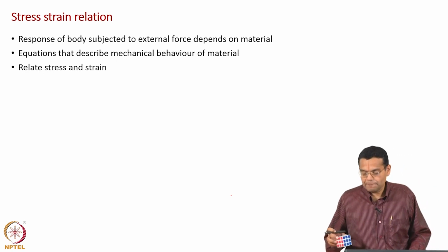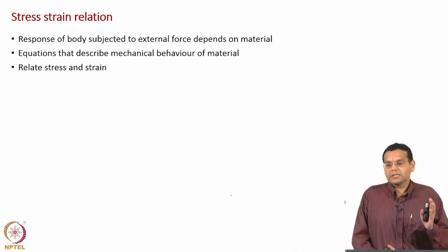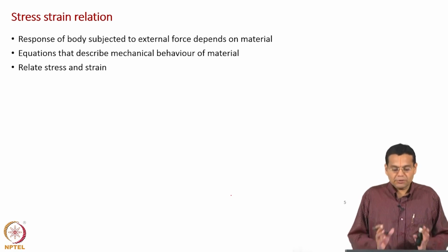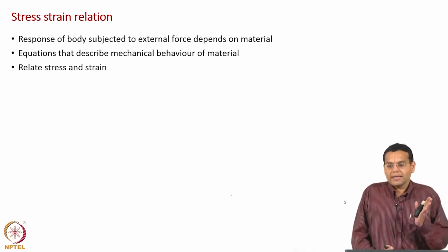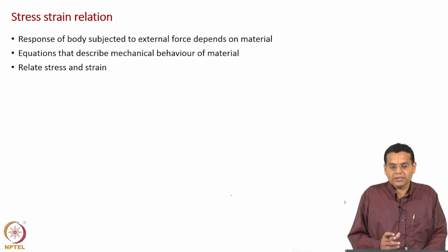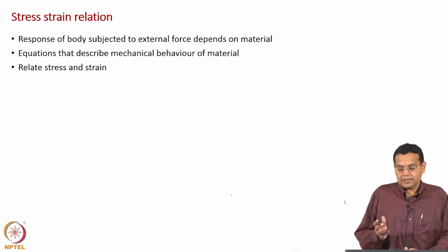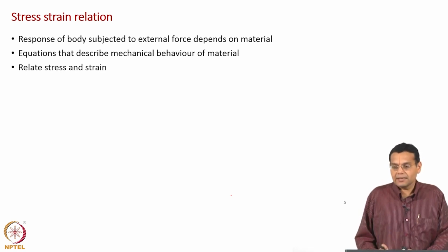and the moment we talk about a material, we need to bring in properties of the material. Okay. When we first came to solid mechanics, we discussed surface forces, surface stress vector in terms of stress tensor, and throughout the discussion we never focused on what material we are discussing. We just discussed it could be a plane inside a solid object, and then we characterized that intensity of force in terms of stress. Then we came to strain. There again, we discussed change in length, change in angle, which we call deformation, and quantified that in terms of strain.